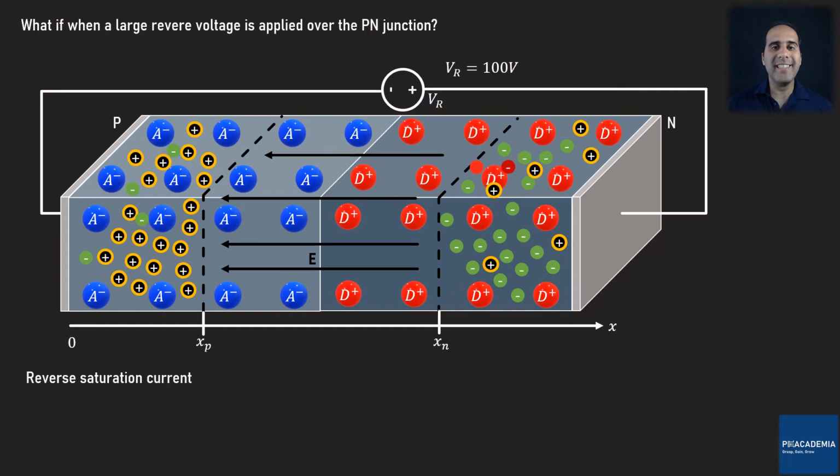The initial kinetic energy was that large that part of that energy is now given to the new generated hole and electron. The new electron collides with another atom, and that causes one more covalent bond to break. This process goes on and on. What we can see here is that an electron is causing too many other electrons to get generated in the N semiconductor. It's equivalent to an avalanche in mountains.